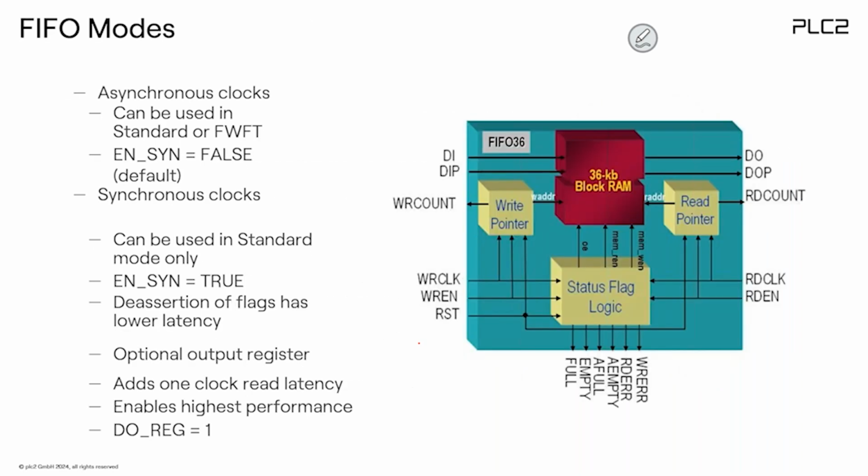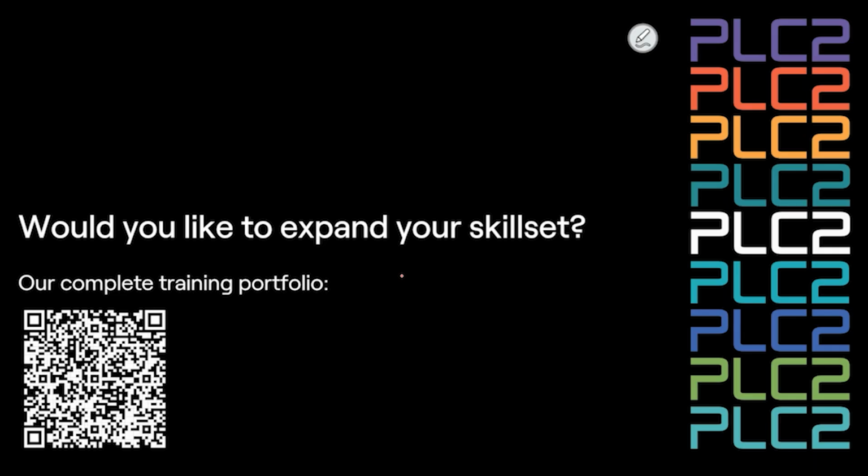And that's the internal operation. We write the data and we read the data, and usually we have two different clocks. So it's a very nice communication between two independent clock domains. That's the concept of the FIFO you would need.